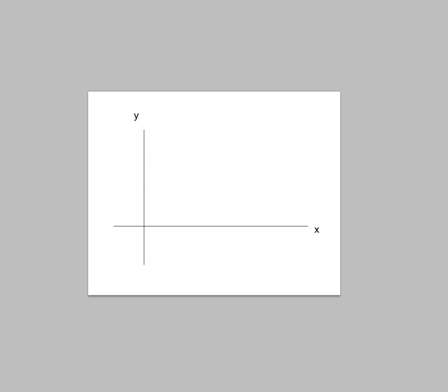In Revit, there are actually 3 origins with their respective coordinate systems, along with 2 norths. The first origin is the internal startup position, or internal origin for the program's internal coordinate system. This system corresponds to the actual internal floating point x and y variables within Revit.